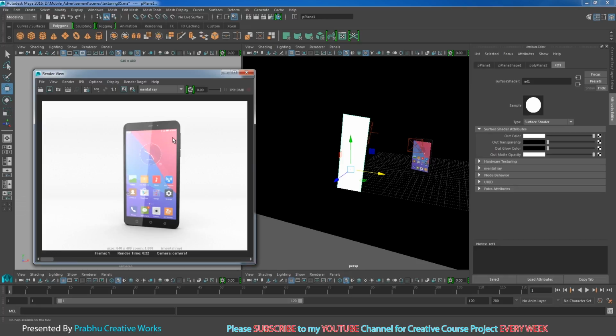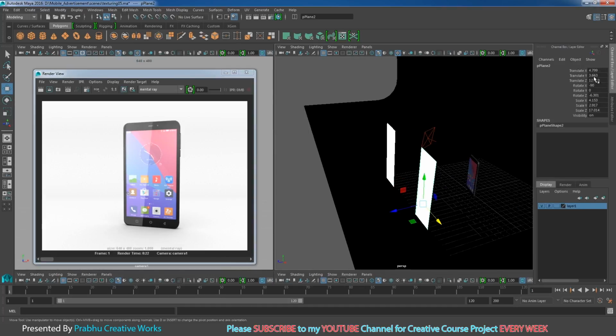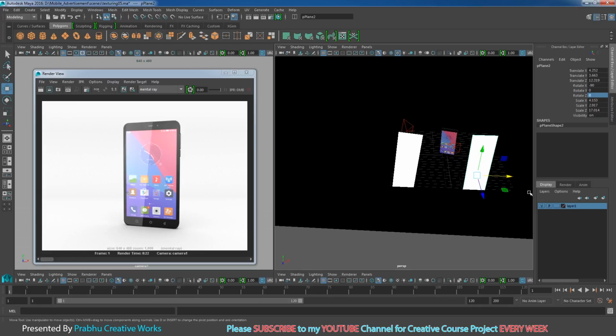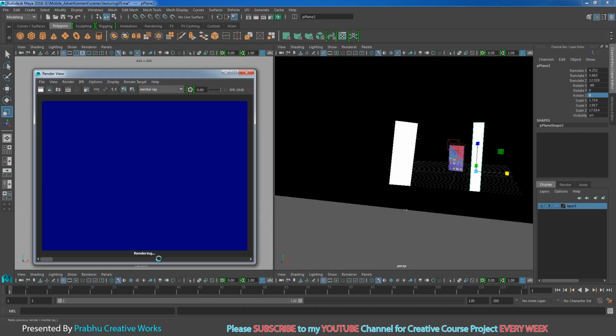So now we want to set another card for this side. So I will press Ctrl D to duplicate. So I will move this card over here. So I want to give rotation 0 in Z. So now I want to take another render over here. So I will move in this side and press R and scale in X, a little bit thin. So for this object I will keep this image and click render.